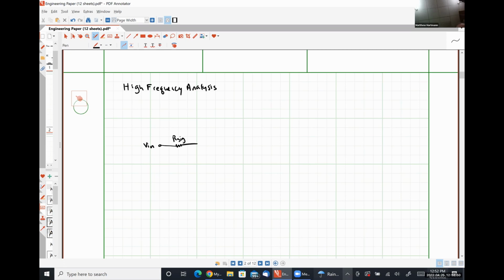And we'll see that C out has gone away in a moment as well. And our parasitic capacitances are now influencing the behavior of our device. So since we have an NMOS transistor, we are going to have 4 capacitors in play here. Between the gate and the drain.